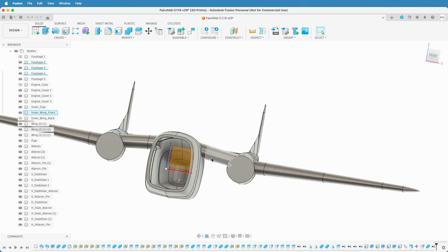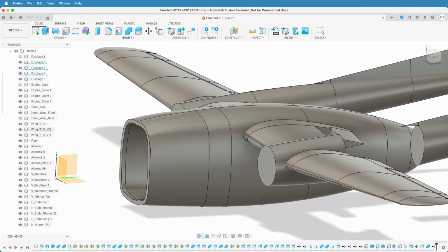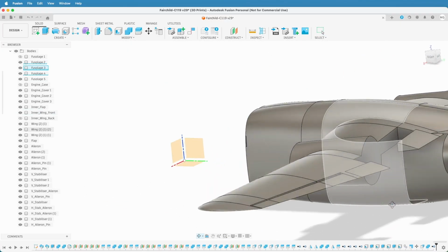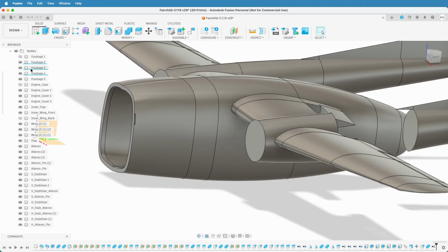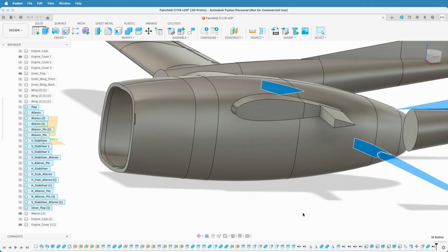So what we can do, you create a sketch there, you offset the edge for whatever you need, and then you probably do the same here, and then you extrude it that way. Have a look. That's in the ring. Take something out.